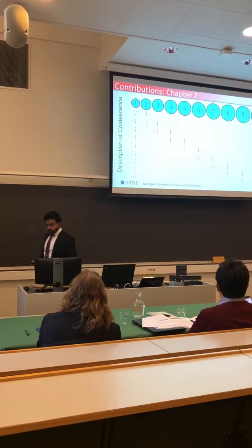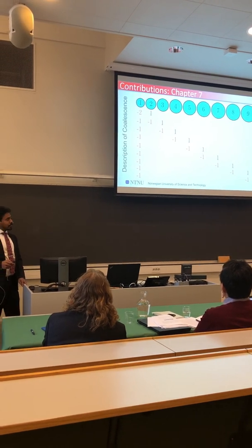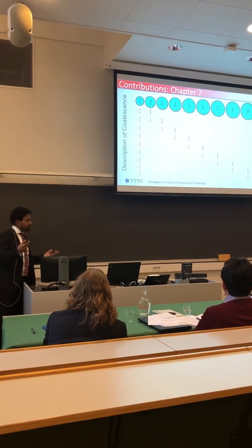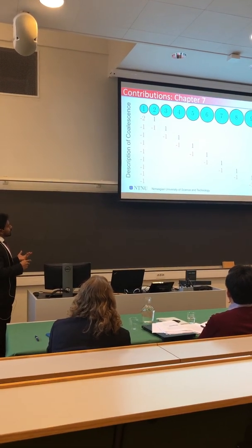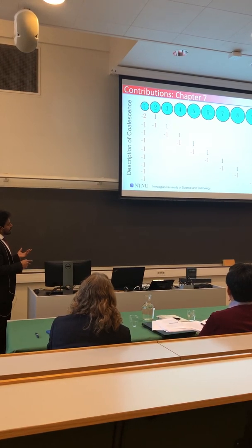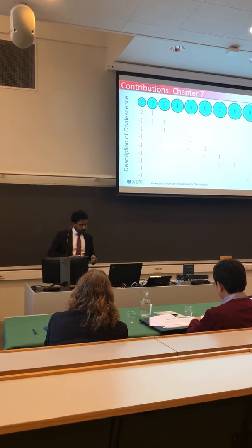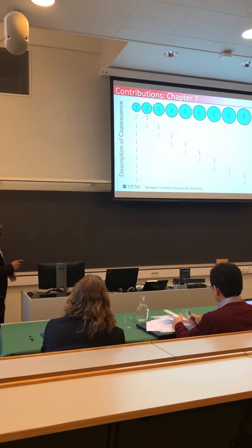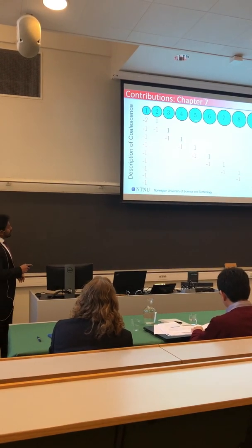One key feature of this work is also the coalescence modeling, which has been done using 10 droplet classes. So what that means is if you take 2 of these droplets, they will form the size of this, and these are real sizes. I made the plot with the right numbers. So if you take 1 and 2, they will combine to become 3. If you take 3 and 2, they will become 5. If you take 4 and 1, they will become 5.